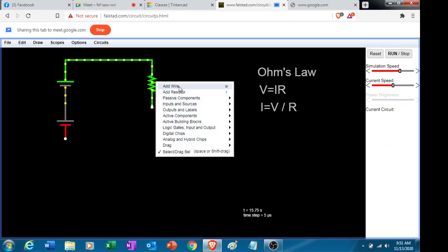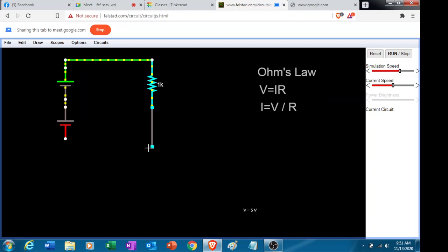It seems to be correct. Never mind the red one because it's registering a correct value. So we now have two voltage sources, two 5-volt sources with just a 1 kilo ohm load, and we're able to increase the current. Can you read the current? 10 milliamps. The previous was 5 milliamps.